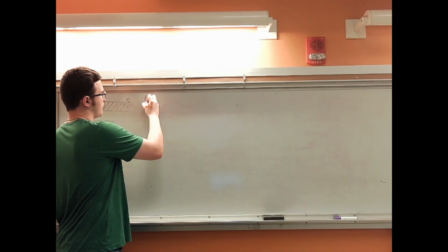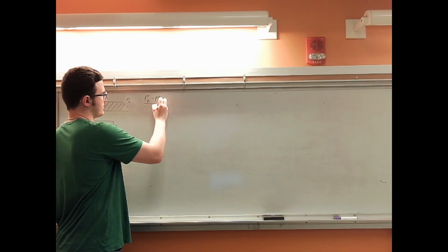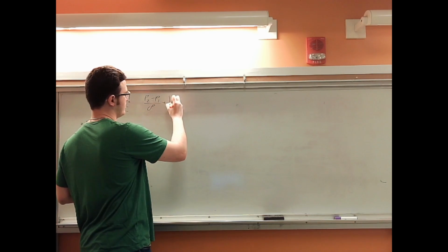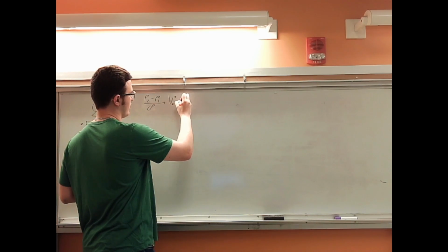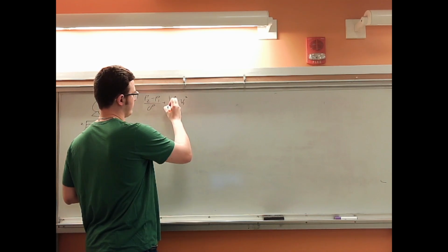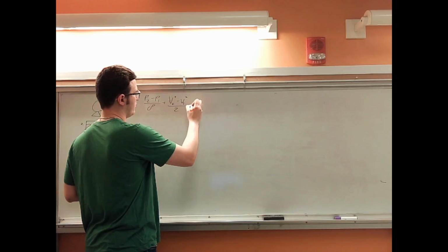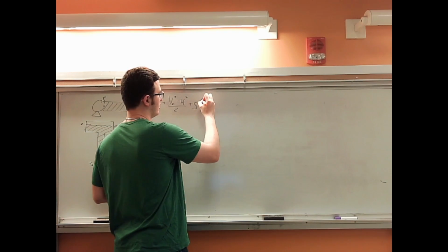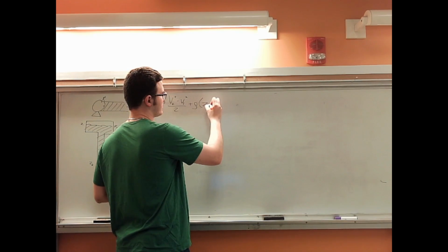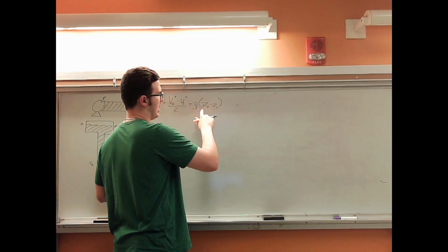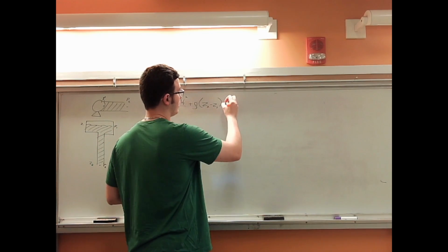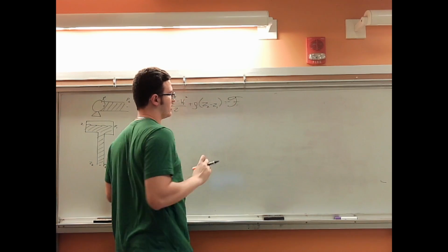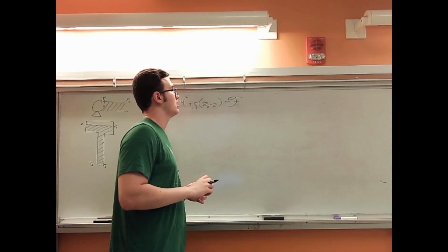The pressure difference between state 1 and state 2 divided by the density, plus the velocity difference squared between states 1 and 2 divided by 2, plus the gravitational constant g multiplied by the height difference between the two positions, z2 minus z1, is equal to, as we know, the negative of the frictional heating.